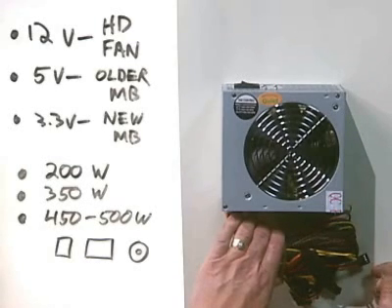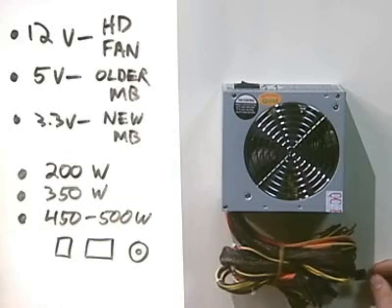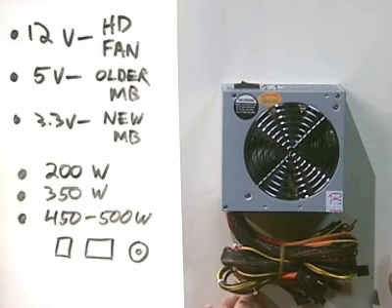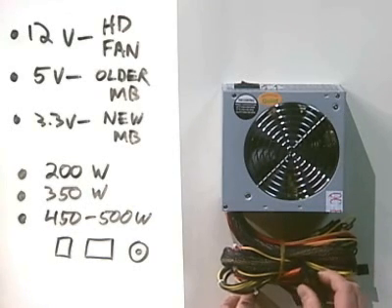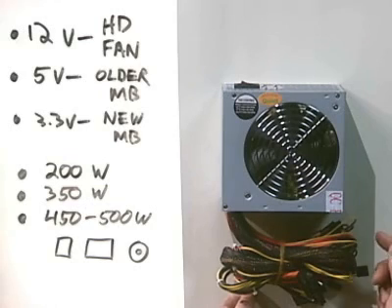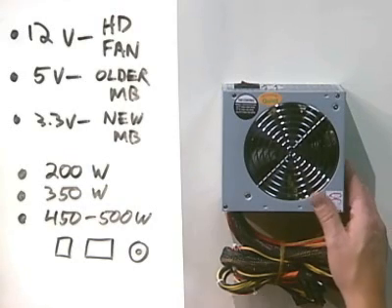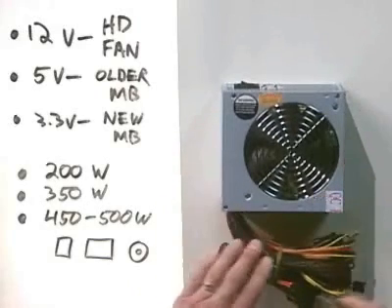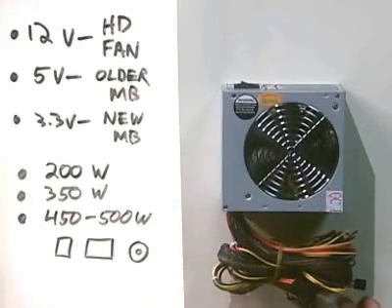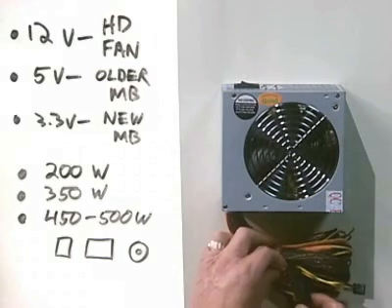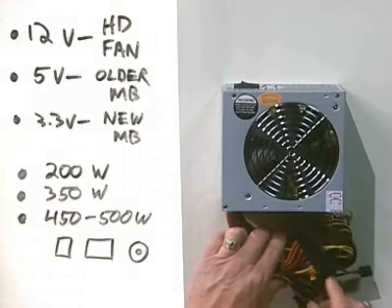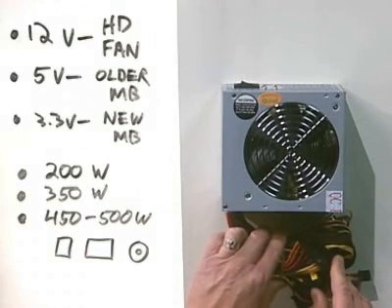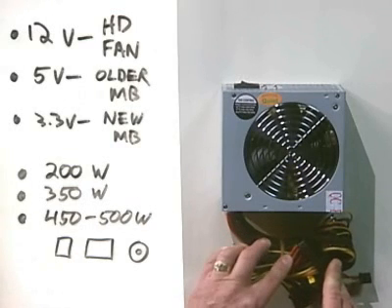Now, older systems didn't do that. In an older system, if you were in Windows and said start, shut down, the system would go all the way down, and then you'd have a message displayed on the screen saying it's now safe to turn off the PC, and you'd have to manually push the switch on the front, which broke the 110 volt power. With ATX power supplies, we have soft power through the power_on wire that allows us to be a little more flexible than that. Now, there's another wire in this motherboard connector that's called the 5V_standby wire, and it's always active.